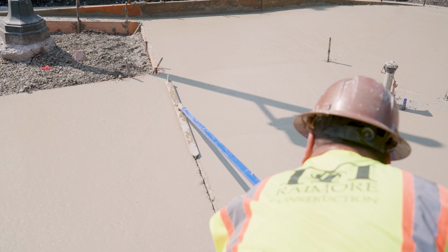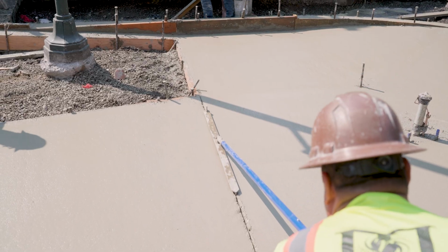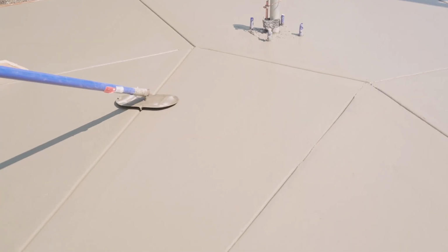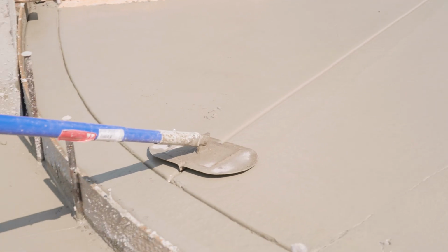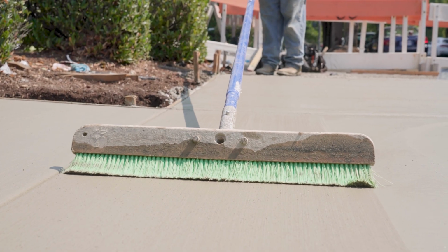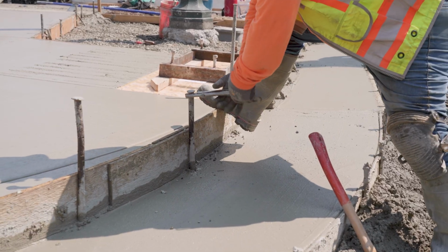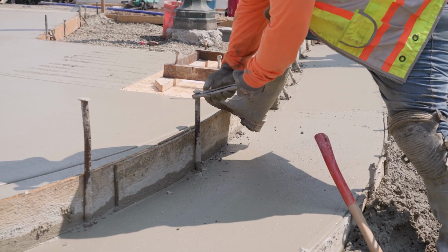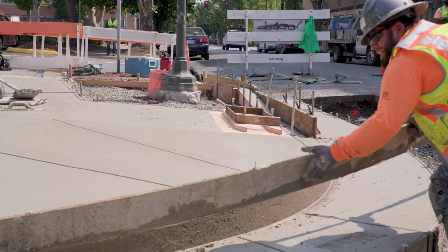Finishing might seem like window dressing, but it's your last chance to ensure against humps, bumps, lumps, sags, lips, or ridges greater than 1/4 inch that can cause compliance failures. Now, the concrete's hardened enough to pull stakes, but not so hard you can't fill the holes and complete the finish. And the forms come off.